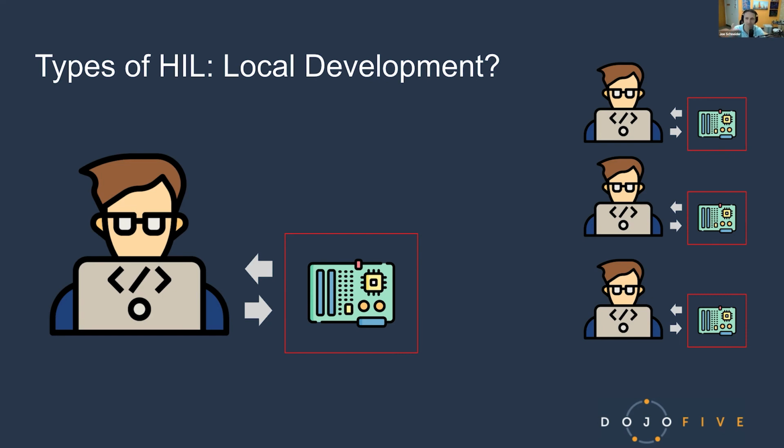But we were able to freeze spray around, and eventually found that if we freeze sprayed the memory, the DDR that was on there, it would happen slightly more. But still not that often. And you're just like, okay, what does that mean? And then they went, when you design DDR into a project, there's all kinds of timing things that can be wrong. It's typically what you'd look for on hardware. But of course we had these other 99 devices that weren't exhibiting this.